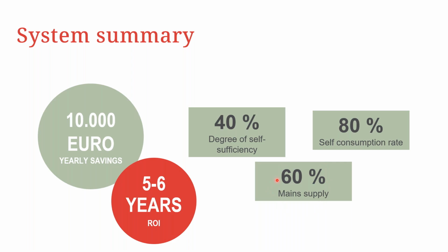Based on this kind of data that you have analyzed, even for your own customers, you can tell the customer that if you did one or two measures for this system, maybe integrate a battery storage system, maybe integrate hot water generation by the Ohmpilot, or if the customer is thinking about adding an electric vehicle, integrate the Fronius Ohmpilot to recharge the electric vehicle either using excess energy or even from the battery storage at night, recharging only to the required extent of the EV battery.